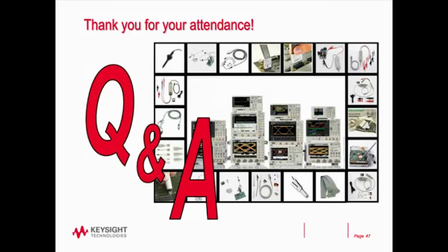Okay. Here's another one. How do you measure the ground difference on the scope? For example, you have the gate driver on digital ground and the driver MOSFETs are on power ground. How would you measure it effectively? I've used differential probes to measure ground difference. I think you could do that.